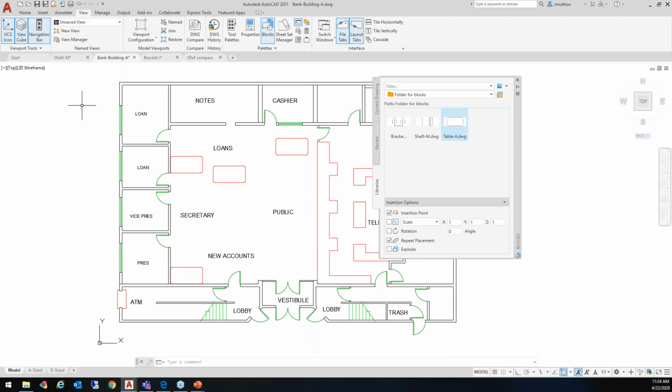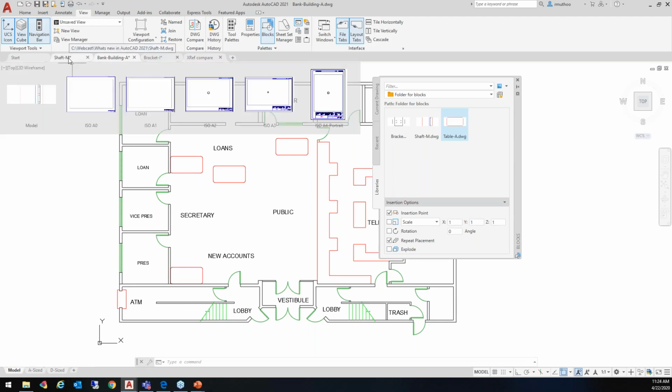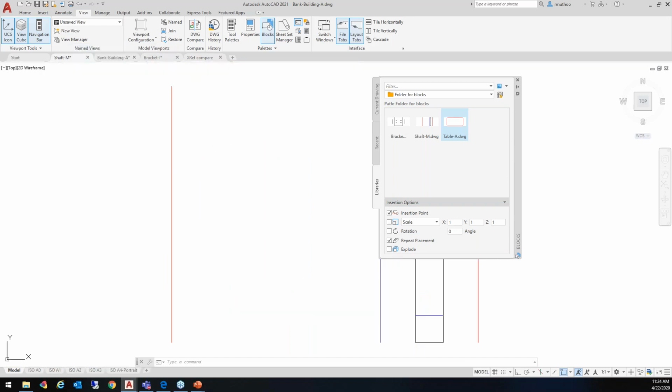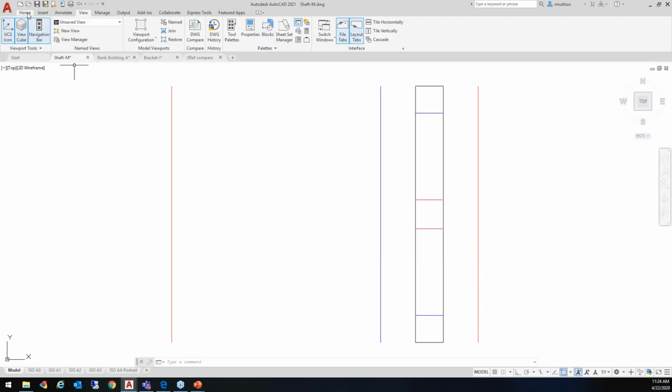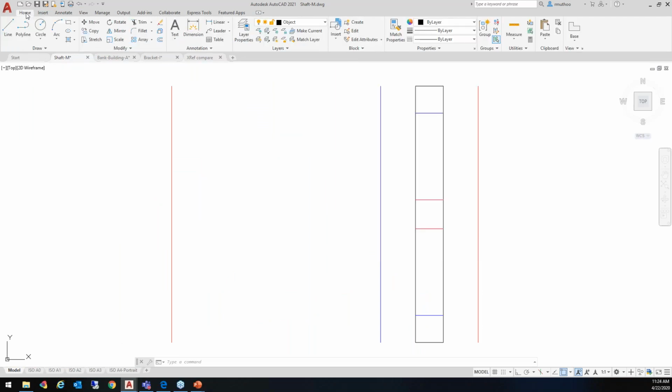So now the trim and extend commands, let's go over that. So let me open another drawing, close the blocks palette here, and it's available, the trim and extend command, as normally they are available through the home tab and the modify panel. So once we start the trim command, till last year, as I mentioned, the legacy was that we had to select the cutting edges first. But here you don't have to actually do that.